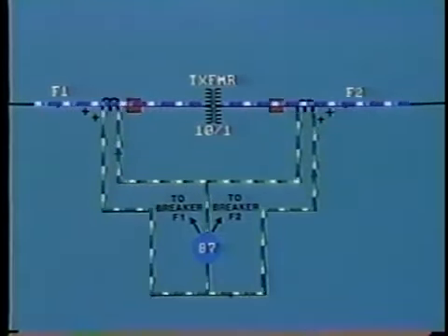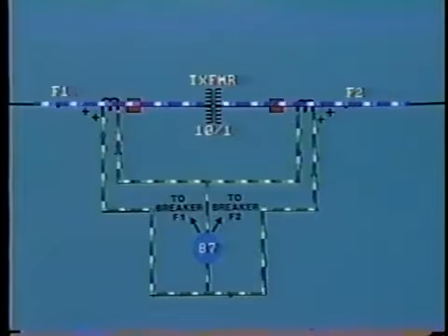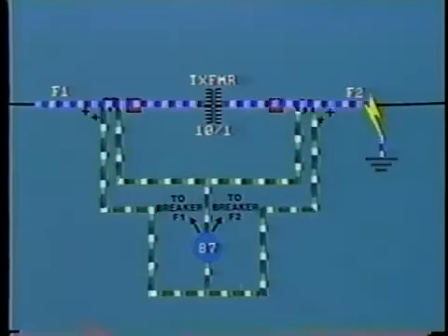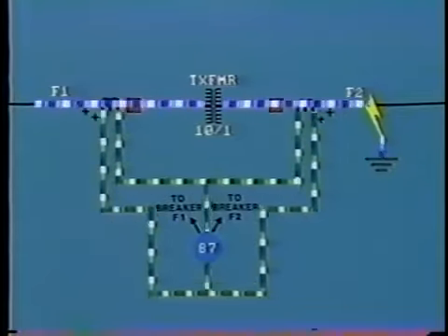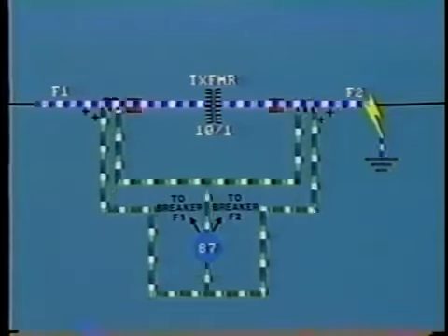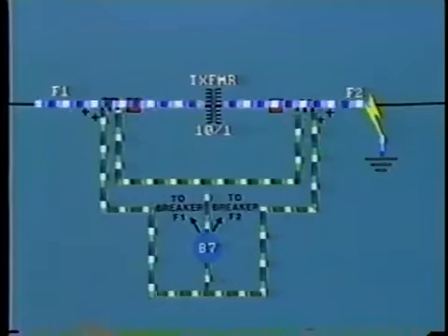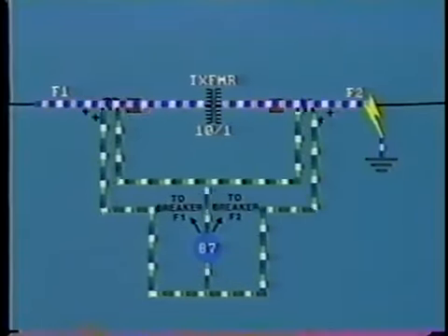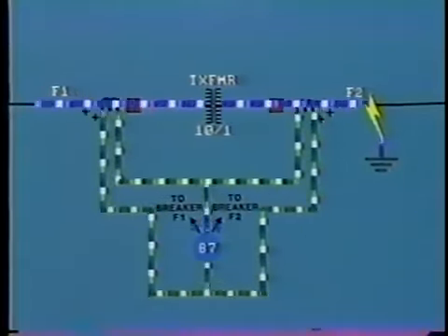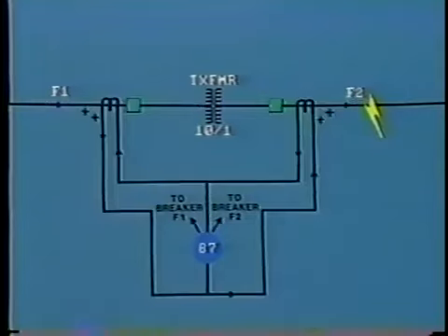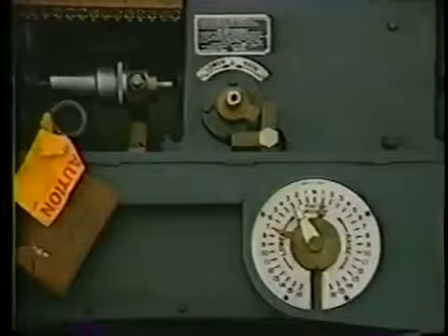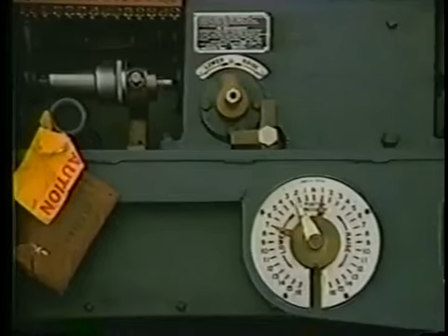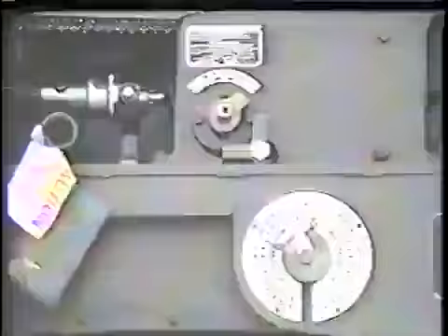and so will not close the tripping contacts. However, things may not be so comfortable where we have an external fault which causes a high current to flow through the transformer. In this case, the CTs will be measuring a balanced condition, but the error will be magnified and may cause the relay to operate. Similarly, transformer tap changers introduce problems with CT ratios.